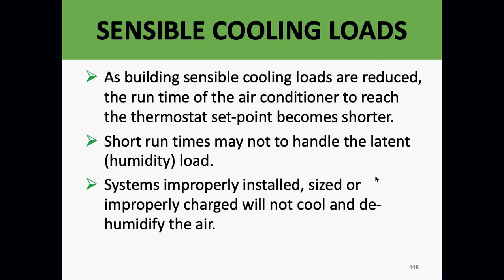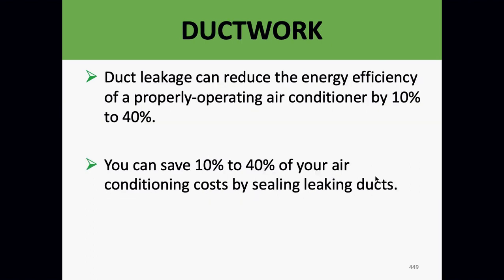As a building's sensible cooling loads are reduced, the run time of the air conditioner to reach the thermostat setting becomes shorter. Short run times cannot handle that latent heat, and we've already talked about this. Systems improperly installed, sized, or charged will not cool and dehumidify the air. So again, we want to be very careful on sizing. Bigger is not always better.